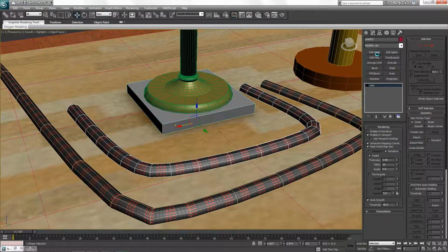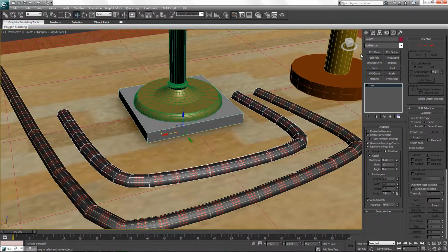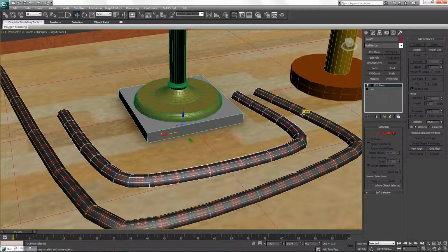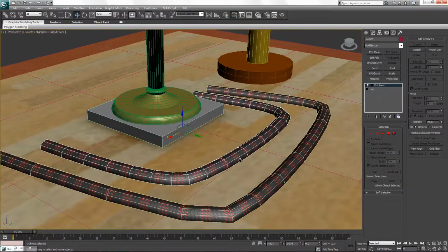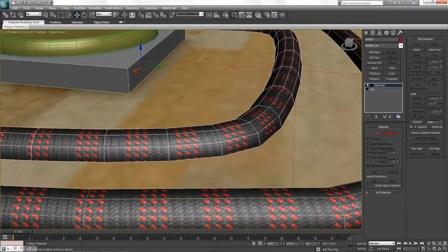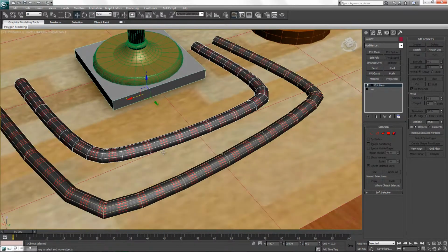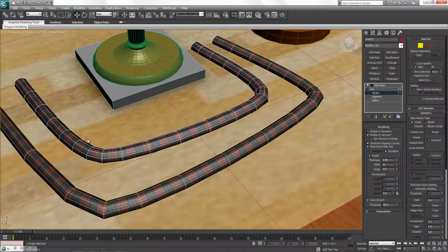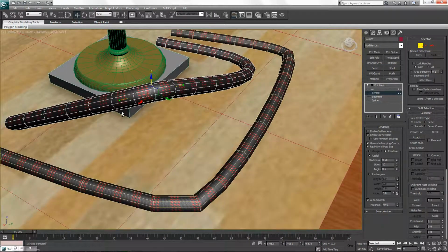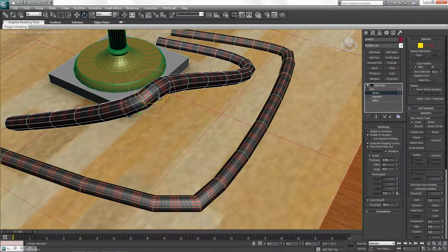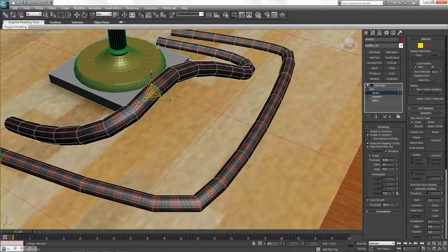The only thing you need to remember is to place an editable mesh modifier on top of the spline, and you'll get exactly what you see in 3D Studio Max, just as a geometry asset within Replicate. Using the editable mesh modifier also allows you to continue making edits to the spline's shape, even after you've cemented it as a geometry asset.